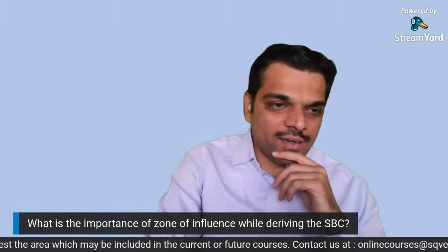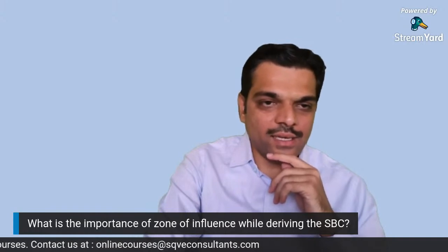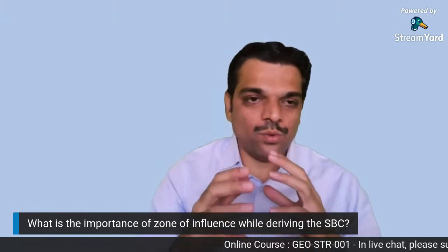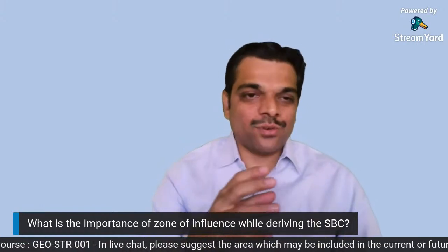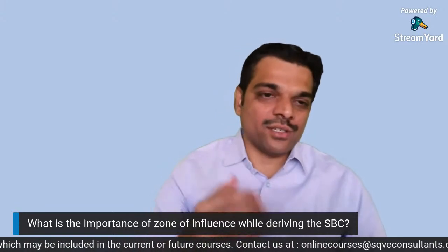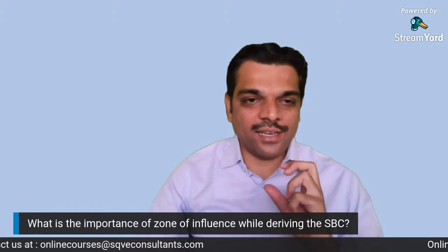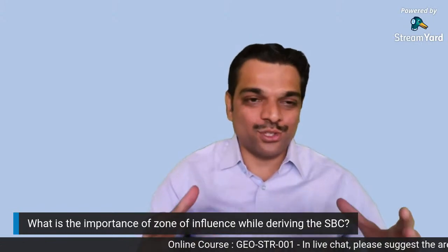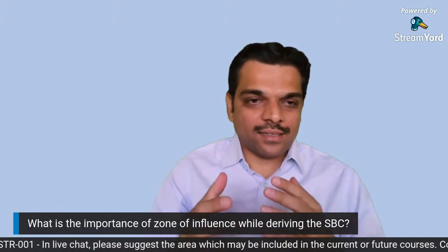Now, this is a very interesting question. What is the importance of zone of influence while deriving the SBC? See, you might have seen in a soil report, I'll just give you a very quick introduction: as the size of the footing increases, the SBC actually goes down. So let us say I have a raft foundation. For my raft foundation, the SBC value will be relatively on the lower side. Now, let us say I'm talking about a very compact plan, in the sense that I do not have the liberty to put foundations of the required size, so foundations are just touching each other.